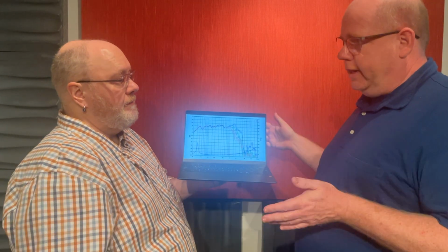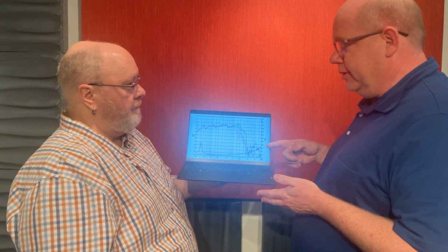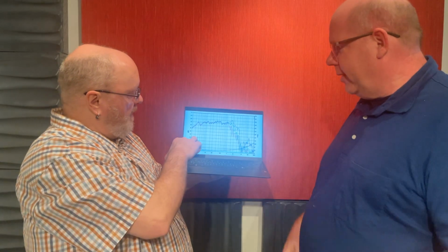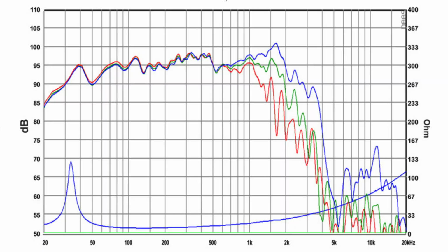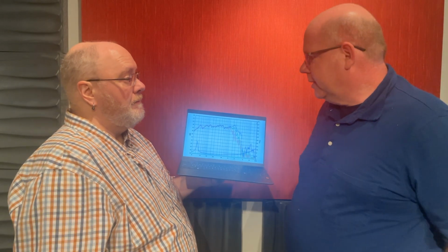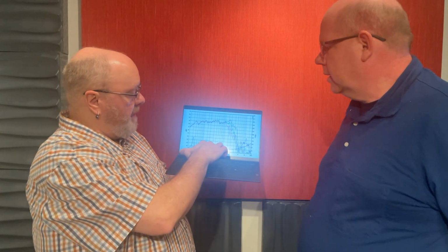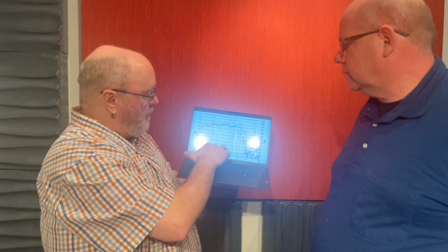That sounds pretty crazy. It's over 100 ohms, and yet somehow we're going to get an 8 ohm driver. How in the world does that work? If you look down here, it is 8 ohms through a good portion of its band. That just happens to be the resonant frequency. At that resonance frequency the driver is doing a lot of work, and the amplifier is not having to do a lot of work. Does the amplifier even register with that high of an impedance? It does, it's still powering things. The low impedance is just, like I said, a nominal. It's at certain points in the frequency band.